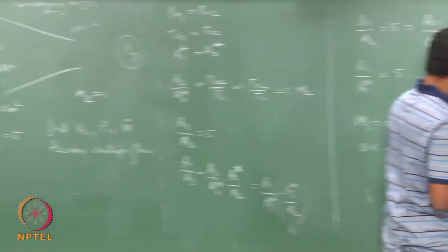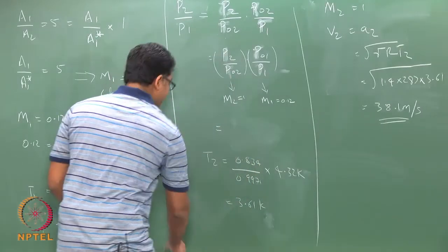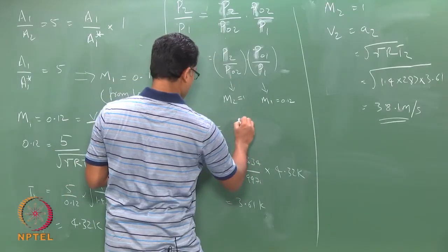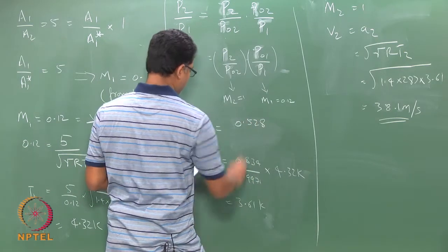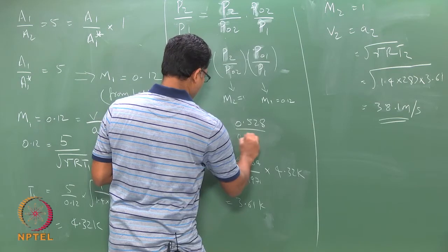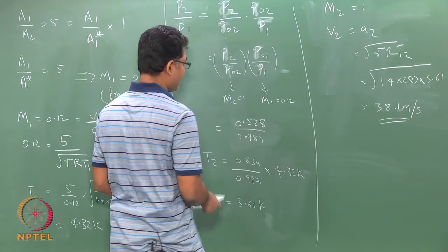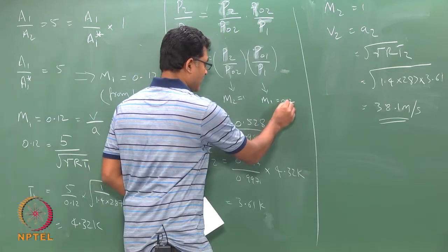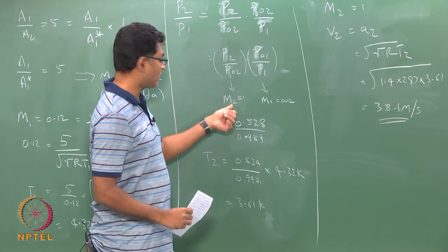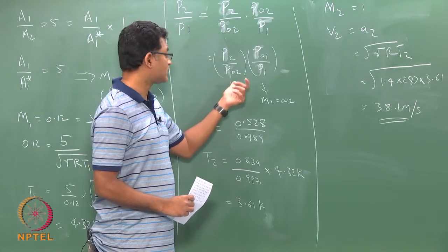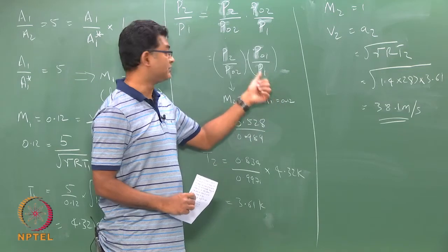So, I do this process and I compute similar values, which is Mach number 1 is 0.528 divided by 0.989 for m equals 0.12. Again look at the isentropic tables where gamma equals 1.4, look for m equals 1, get the pressure ratio, look for m1 equals 0.12, take the pressure ratio. This is the inverse.